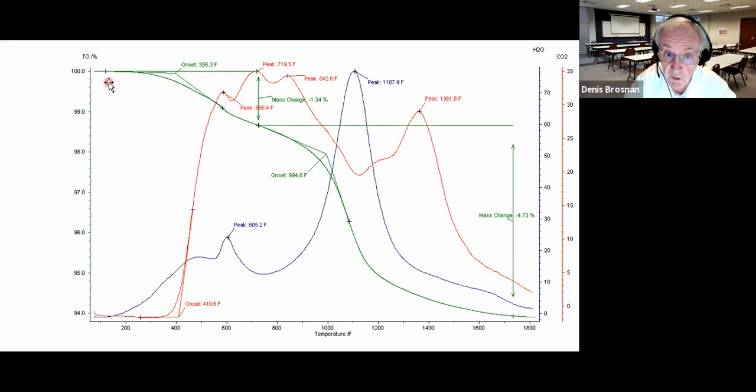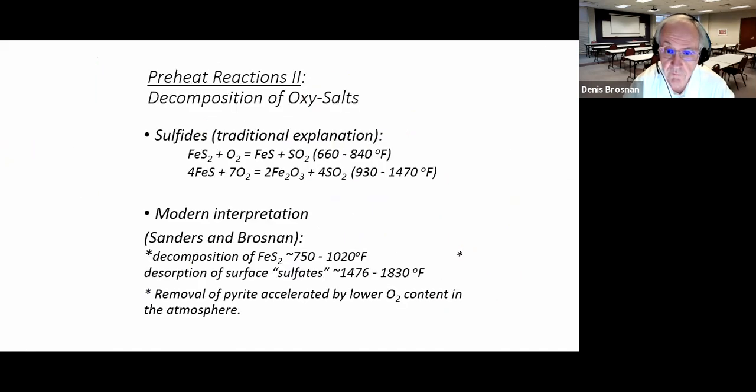It breaks into fragments, and you can see it leaving the ceramic body in the TG curve. They also oxidize in some cases. So you want to give the ceramic time to release these organic phases, whether they're molecules or carbon dioxide, before you have any vitrification take place. Otherwise, you can have some problems.